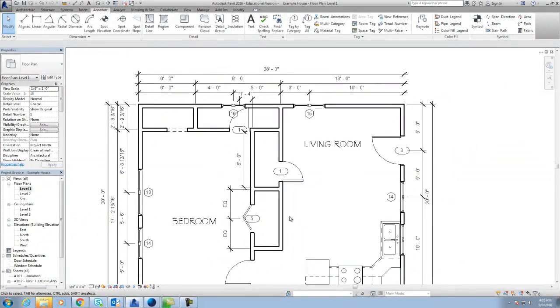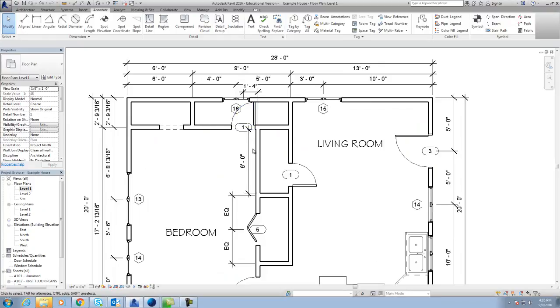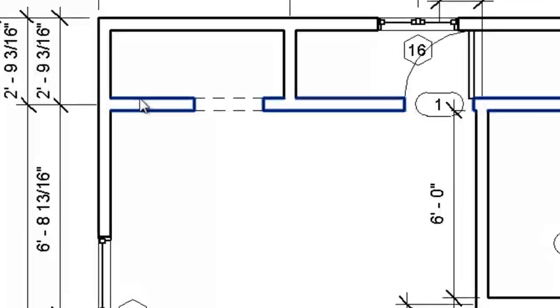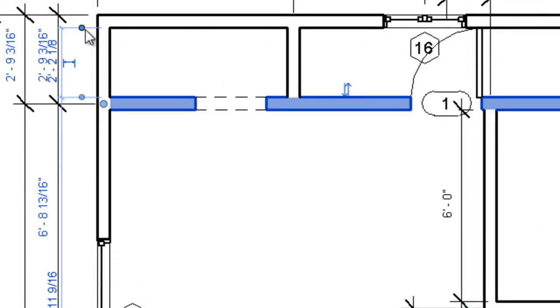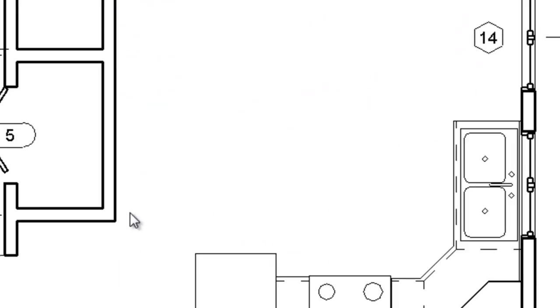Now, looking at some more stuff here, this can't work because this is going to be our bathroom up here, and the problem I see with it is our bathtub. The smallest bathtub you can get is 5 foot. So it needs to be across here. So this needs to be 5 foot. So I'll click on this wall, and interior to interior, I want to change it to 5 foot. And it actually moves some stuff down. And I want to keep this thing at 6 foot.